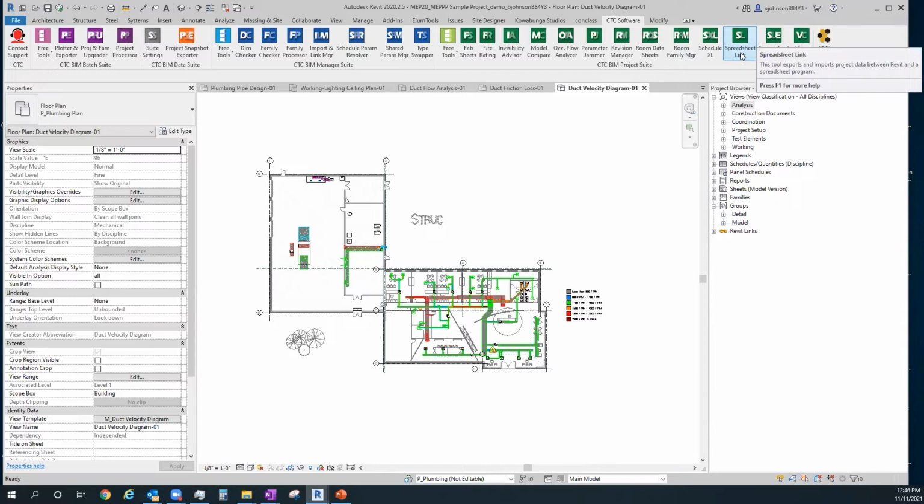I could even export that out to Excel, have somebody who's not a Revit user make massive changes for me, import that file back in, apply the changes, and have all the parameters in Revit be updated that have been affected, as long as they are changeable parameters. If they're parameters that are being driven by formulas and things like that, usually we can't do anything to those because they're being driven by other values. But we can usually change the values that drive the formulas, right? So if we know what those are, what they should be, we can make massive changes to the Revit database, which updates the families, which updates the schedules. Everything is smart at that point.